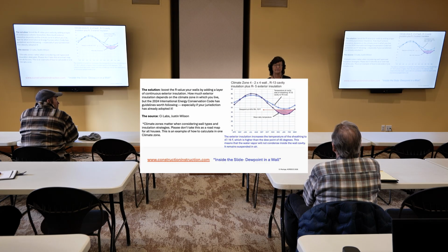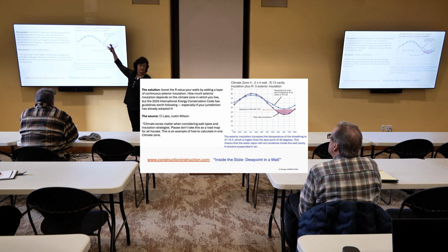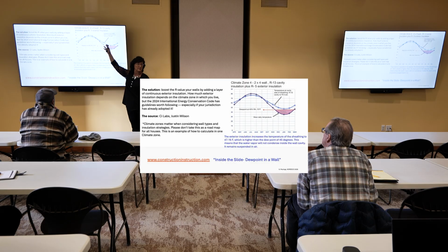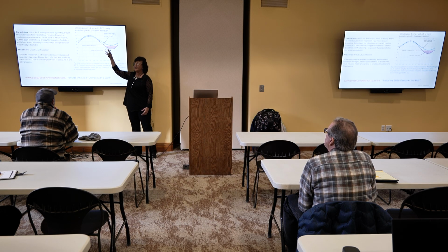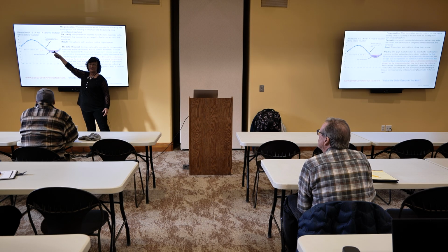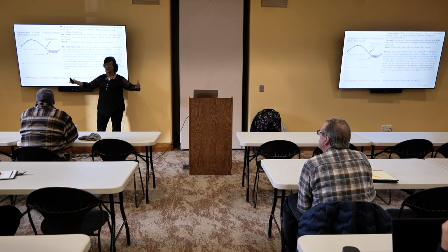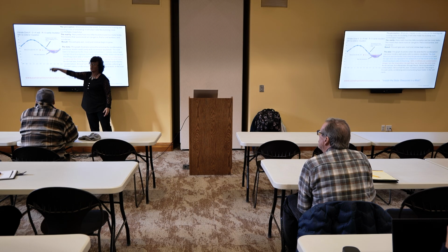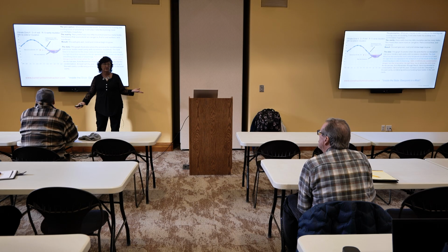How's the wall going to dry if it does get wet? Well, hopefully it'll never get wet. Well, how are we going to know if it's going to get wet? We're going to calculate the dew point and figure out where that's going to be, right? If I have it down here in the pink, and I have a vapor barrier on the inside because it said to put a vapor barrier on the warm in winter side in my climate, and I have a vapor barrier on the outside, and I condense inside the wall, I have no way to dry.